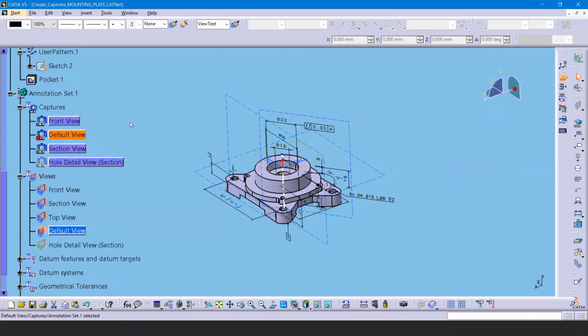All right, our last thing to go through here is to create a surface roughness view. So that's going to be going right down the middle of the part. So it's going to be on my ZX plane. So once again, I'll click on my view from reference. I'll go grab my ZX plane. It's towards the top.